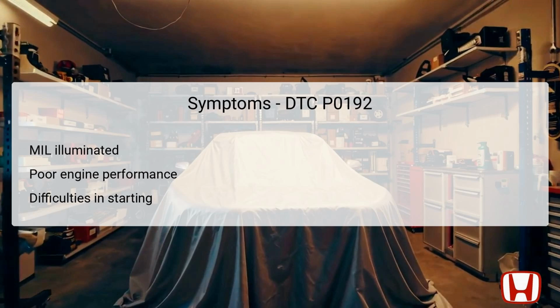delivery. Another potential symptom is difficulties with starting the engine, as incorrect fuel pressure can lead to inadequate fuel being supplied at startup. Each of these symptoms serves as important clues in diagnosing the underlying issue, and recognizing them can help technicians arrive at a solution more efficiently.